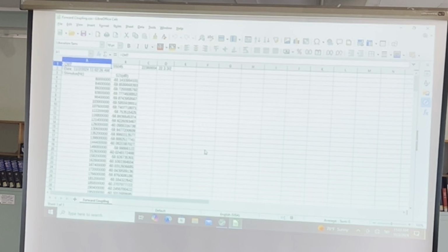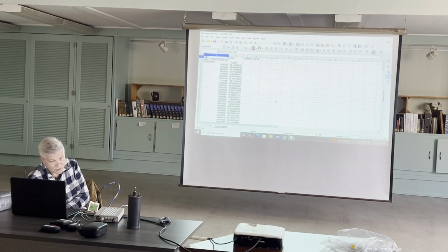So at 80 megahertz, the actual loss is 60.141 dB, out to a lot of decimal places. And you'll notice that it's not precisely 60 everywhere. There's some ripple in it. You know, it drops to 59.85 and so on and so forth. Now that's important to us when we make a power meter. We need to know exactly what the coupling loss is at a particular frequency.